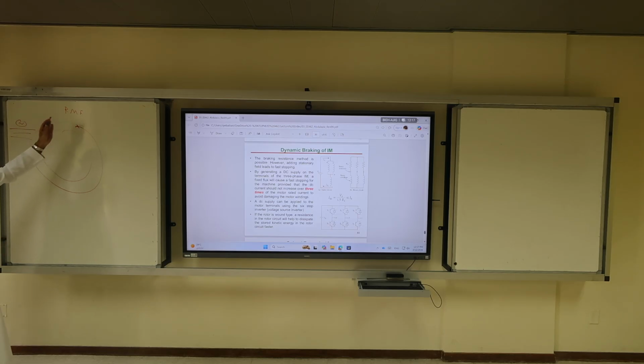So the rotating MMF rotates, sometimes the north and south are here, after some time the north and south are here. The squirrel cage rotor would align and rotate until the slip is satisfied, but because of their rotation, the bars or the wound rotor would have current IR that would also generate a magnetic field that would chase the N and the S and follow it.